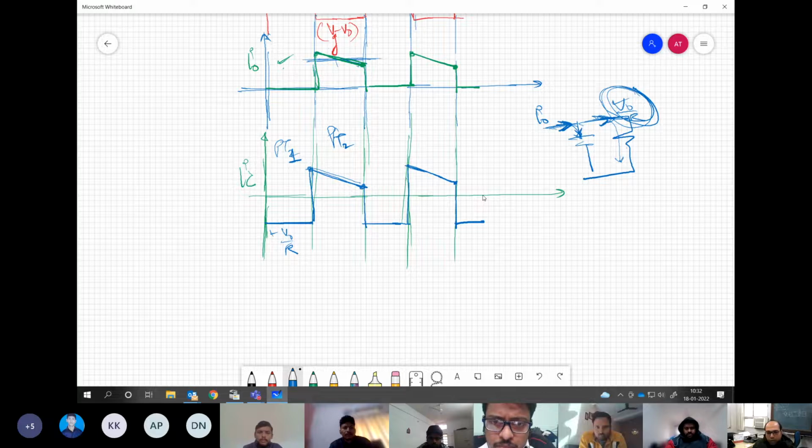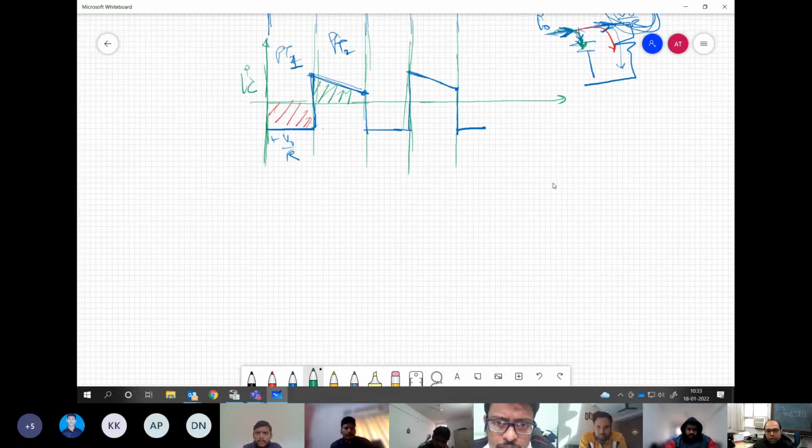Yes. Now, the capacitor voltage, if you see, during this discharge cycle, if I mark this area, the voltage will reduce. Why? Because there is current flowing out from the capacitor. And during this time, when the current is positive, this will basically charge because some current is flowing into the capacitor. So we will have the capacitor voltage going discharging, not negative.